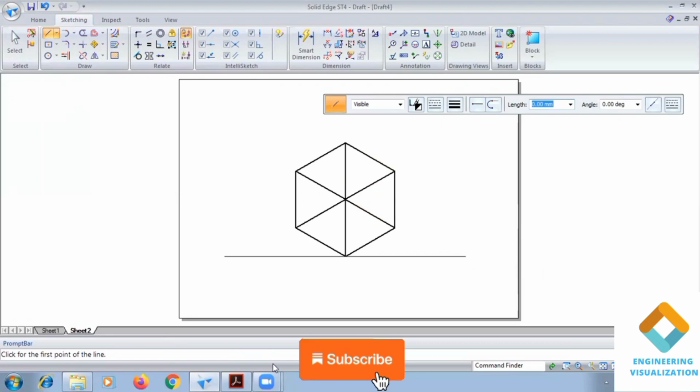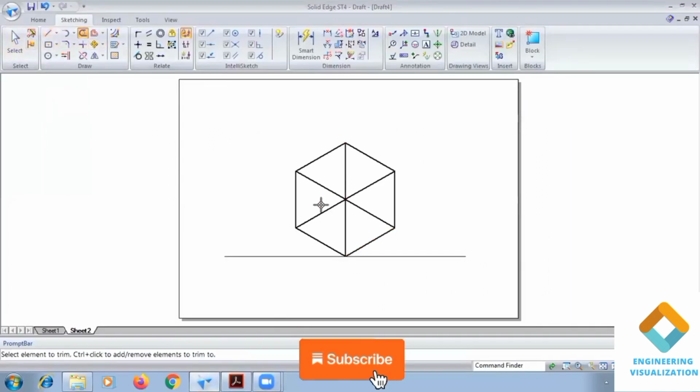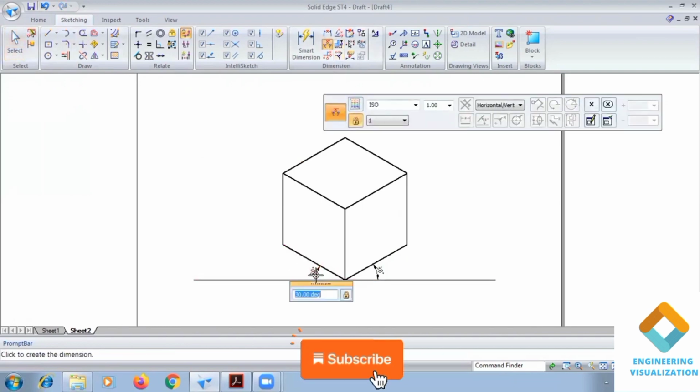Above it, centrally, we need to place the sphere. That also has dimension 50. But guys, you know that the sphere will be constructed with the actual scale, but the cube we need to convert into isometric here. That is the important thing. You can keep it like this, then you can show the angle. This is one of the basic first problems of isometric projection, guys, and this problem can be asked in the exam.